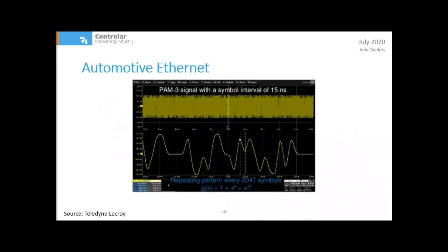The main difference between Automotive Ethernet and Common Ethernet is the use of a single differential pair for the automotive. Both 100BASE-T1 and 1000BASE-T1 are encoded in PAM3 with 66 MHz and 750 MHz clocks respectively. These frequencies enable the possibility of using low-cost wires. Also, the spectral efficiency is higher for Automotive Ethernet, reducing the emitted EMI noise, removing the need for shielded wires. Both uplink and downlink data are transmitted at the same time in a full duplex communication on the same differential pair.